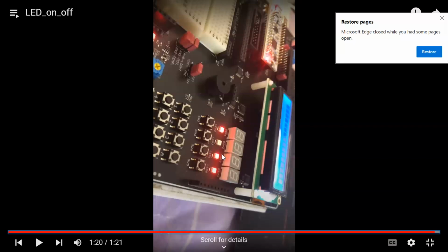I'm going to use what we call time multiplexing for the 7 segment. I want to display a number here in the 4 seven-segment displays. I'm going to use the same idea. We have 4 seven-segment displays. I'm going to put only this one on, the others off, and then this one on, the others off, and then this one, and this one, the others off. If I do it very fast, you will see a very stable number. In reality, it's not that only one is on at a time as it looks. Okay, so this is very important to understand what we are going to do later, okay, guys.